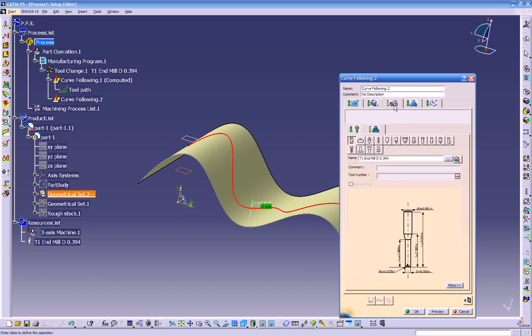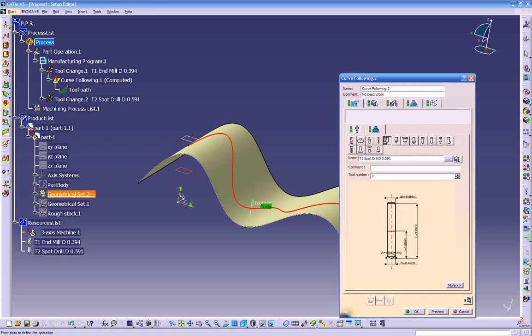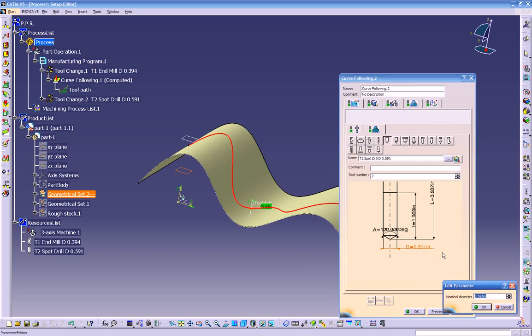And usually when I scribe the part, I usually use a sharp point. And let's use something with a sharp point, like a center drill or a scribe tool. Let's use this just temporarily. To scribe it, it doesn't really matter in our case right now because this is not a finished part.